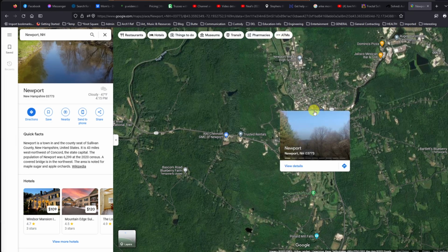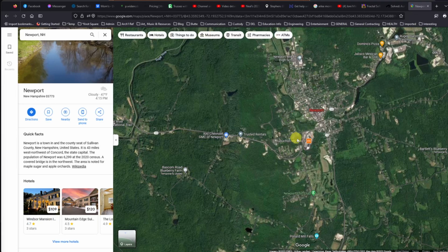But once I've talked to the county or the city, whichever this property happens to fall in, because let's just say they told me that they were going to be here. They didn't have an address yet. I made the assumption they were in the county, but truly they were in city limits. Well, then I'd need to contact the city and say, okay, what are your requirements? And maybe jump on their website. And sometimes if they're organized, they have a checklist. If they're not, they can have very little information to go on. So then I will contact the city itself, worst case, and say, I need to know what's required for a residential building permit, and then discuss with them.